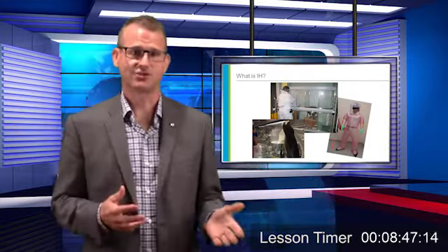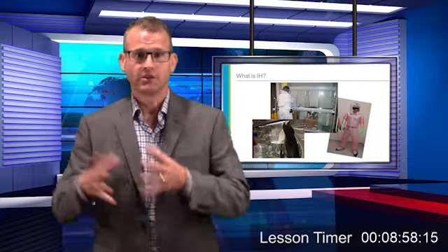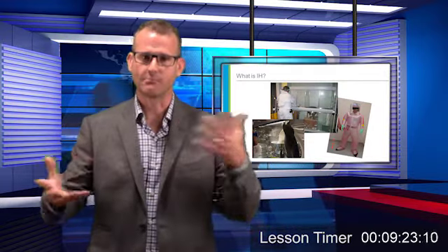And these assessments will be conducted by performing a containment test, or a challenge test as we sometimes call it, using a surrogate material such as lactose or riboflavin or some other compound, maybe even like naproxen sodium, or some other dry powder that really behaves like an active pharmaceutical ingredient would. So we'll still use our senses to observe what's taking place in this particular challenge test, but we're also going to try and determine where the weak points are in the system from the overall design test. Really, we rely heavily on the data that comes out from the sampling test itself and not so much what we see, but certainly both of those go hand in hand.